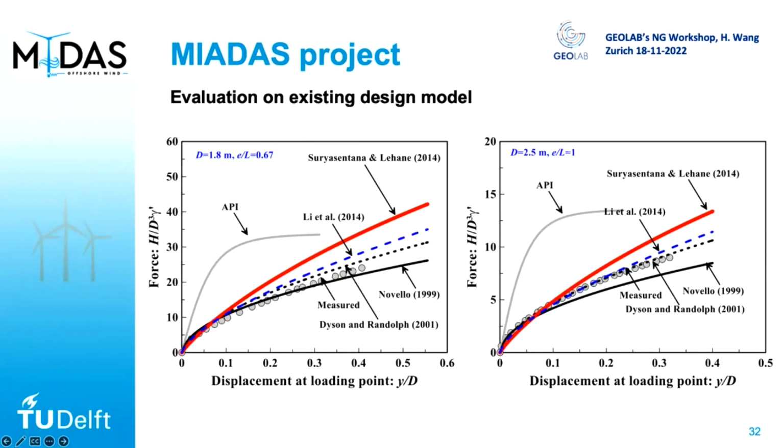So most times the PY curves still contribute most. But if in the future we really go to that large and short pile, we need to incorporate all the other components. And that's already part of this project, I think, our design method called PISA. So that's the answer, yeah.